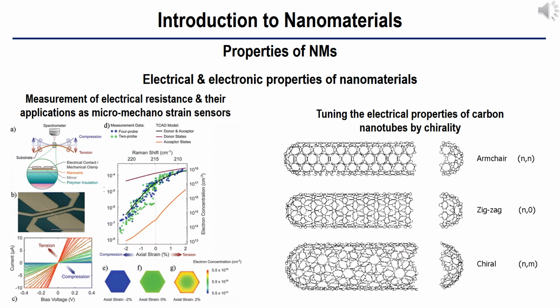Electrical properties of nanoparticles cover the fundamentals of electrical conductivity in nanotubes and nanorods, carbon nanotubes, photoconductivity of nanorods, and electrical conductivity of nanocomposites. One interesting method which can be used to demonstrate the steps in conductance is the mechanical thinning of a nanowire and measurement of the electrical current at a constant applied voltage. The important point here is that, with decreasing diameter of the wire, the number of electron wave modes contributing to the electrical conductivity becomes increasingly smaller by well-defined quantized steps.